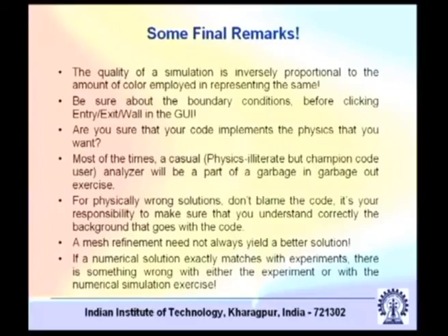One should be very careful about the physics that has gone into the CFD code. Once you consider the physics, one of the important considerations that comes is the boundary condition. Be sure about the boundary conditions before clicking entry, exit, wall in the GUI, or inflow, outflow, wall. This is very tempting, because what we see very commonly is that you click, for example, an outflow boundary condition where it is not exactly outflow. Let us give an example.